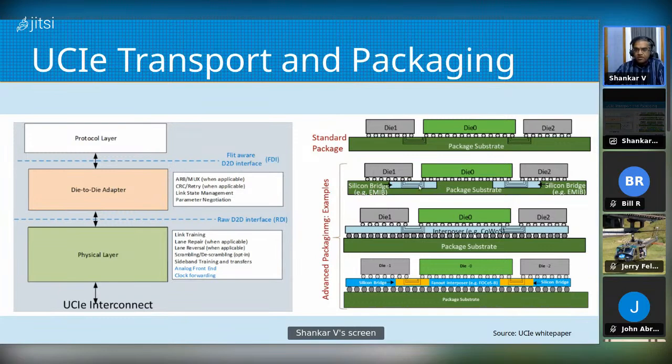And then these wires are similar to wires deposited on any other die. So this is another piece of silicon. Just think of it as being flipped upside down, and the connection is made between this top die and the bottom die, and it's just a sliver to connect the number of signals on this side to the other one. And you have another one for however many die-to-die connections you need. So this is one variant of what we call 2.5D packaging. So this is 2D packaging, so everything is in 2 dimensions, and this is 2.5D.